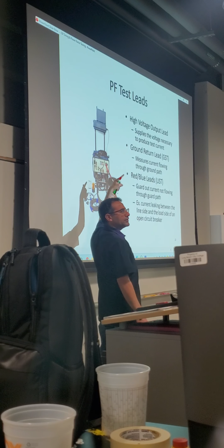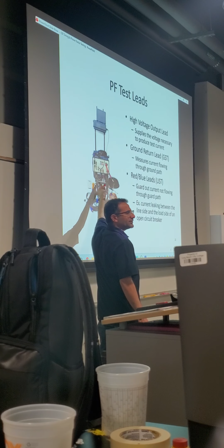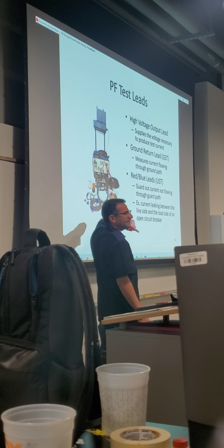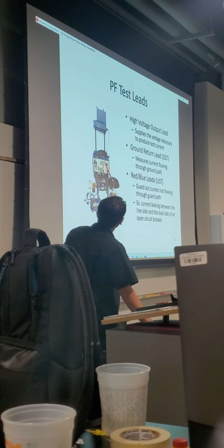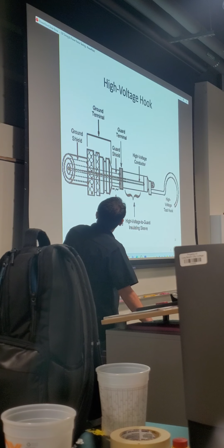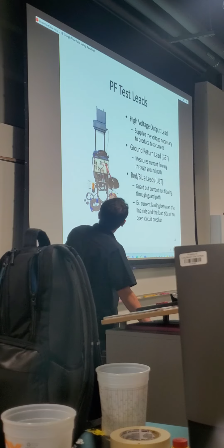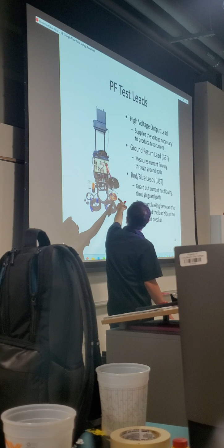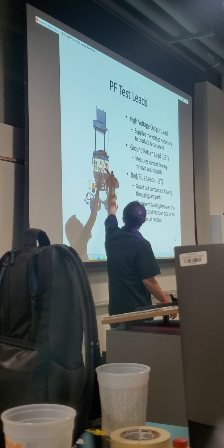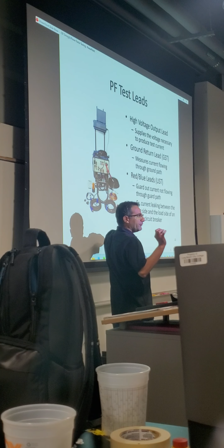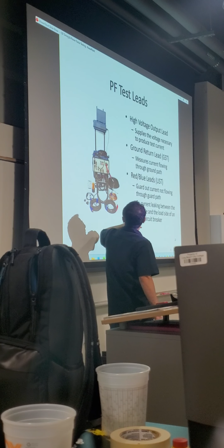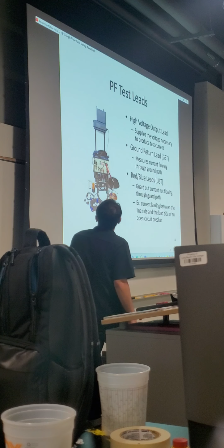It's kind of portable. It's about, let's say about 70 pounds. It's not that heavy, 60, 70 pounds. You have a lot of leads, so you're gonna connect it, and this one is the ground lead. Ground always goes on the test instrument first. Ground is gonna be made first, and it's gonna be broken last.